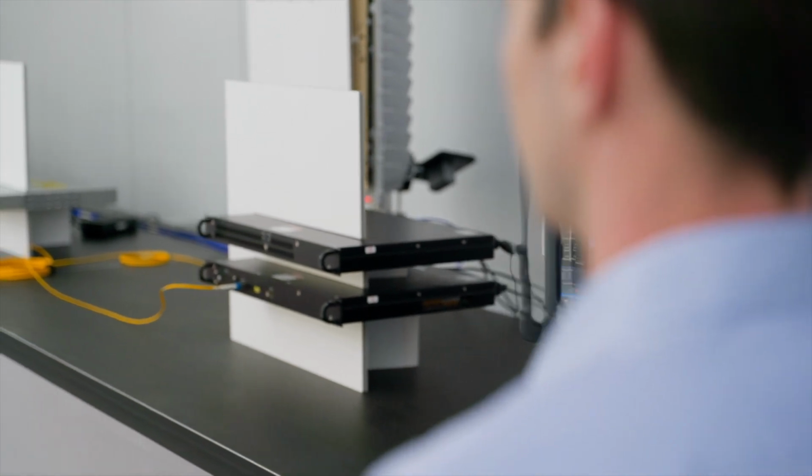The O-RAN fronthaul interface consists of 4 separate logical links or planes. A control and a user plane, which contain the actual radio signal, a synchronization plane, which keeps the RU and DU in sync, and a management plane which controls and monitors the RU. We call these planes the C, U, S and M plane. Now let's take a look at the setup we've put together.